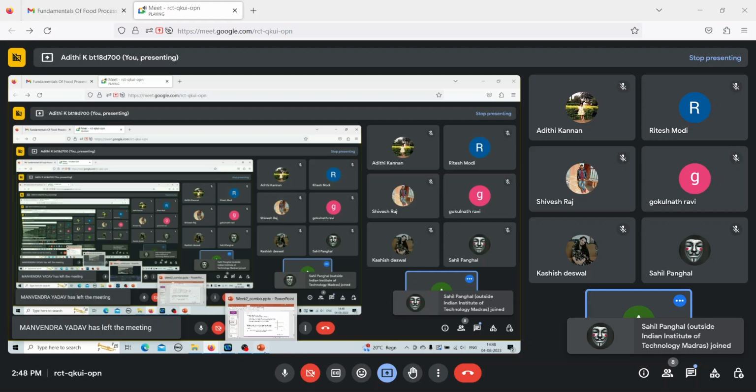Yes, an elastic material's stress is proportional to the strain, whereas in the case of a viscous material, the stress is proportional to the rate of strain. We already know what the strain is, so your stress is going to be proportional to this for an elastic material. For a viscous material, we need to find out the rate of strain.